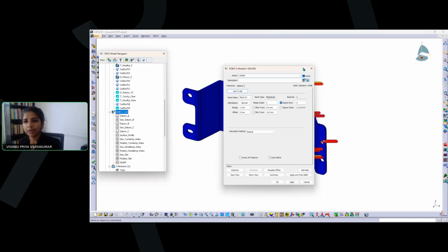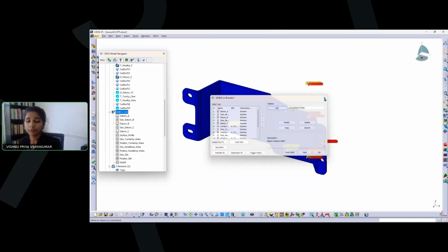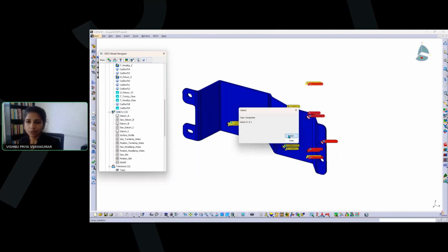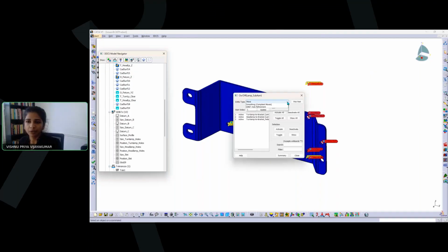This setting will be helpful if a user is trying to create a new model by adding new GD&T. But at the same time, if you have an existing model where you have all these refinements active or inactive, and you were looking for a way to control that, we added a setting in our MTM on-off function. When you click that and go into a part, under the entity type, if you hit the drop down, we have the option for GD&T auto refinement. When a user picks a part, they can see the list of GD&T that have these refinements turned on.